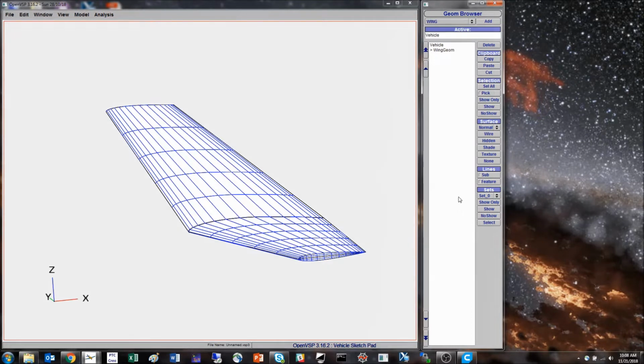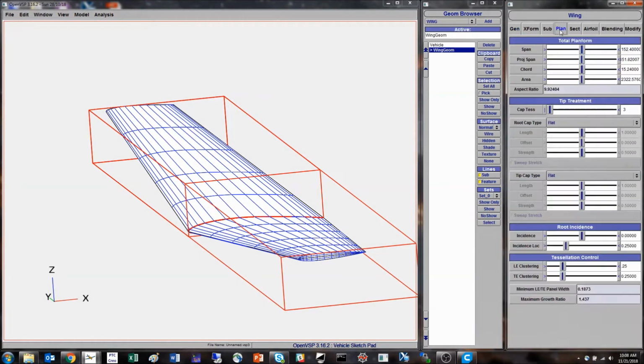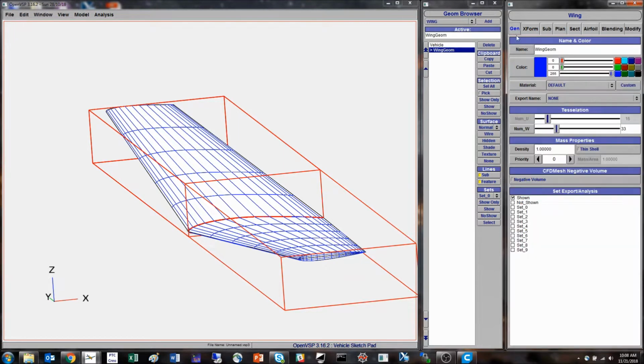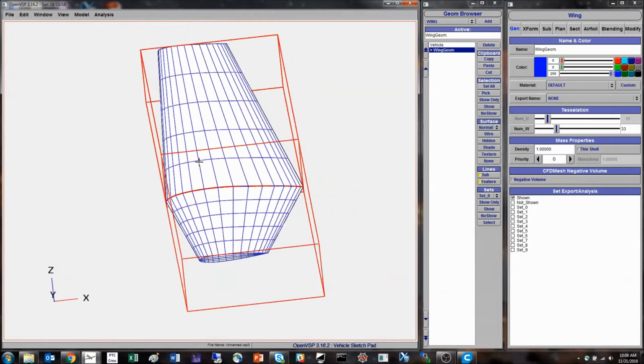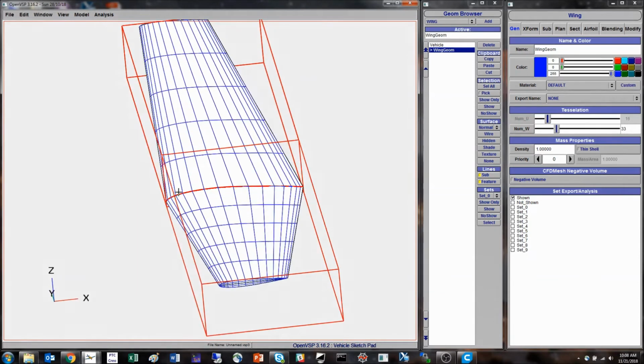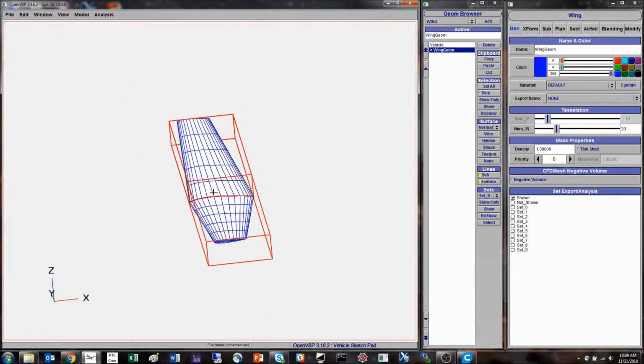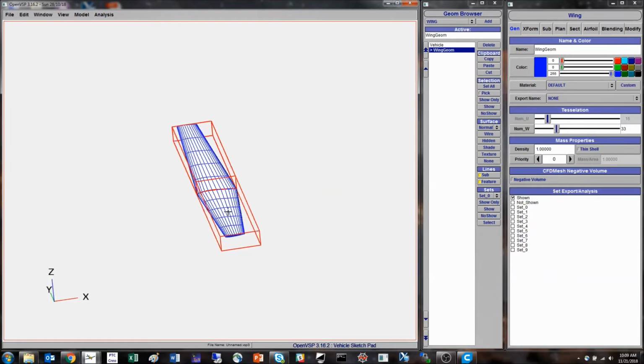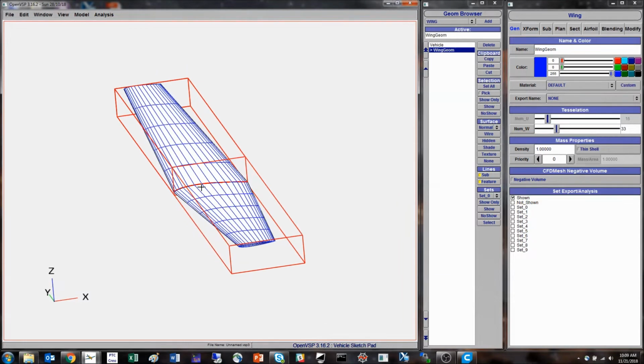So to begin, we've got the model that we finished with in the wing design video here that's already scaled for millimeters at a 6-inch span. That's 152.4 millimeters and an area in square millimeters. Now, you'll notice that the wing looks right. It's got a nice sweep, it's got a nice taper ratio, the aspect ratio looks pretty good, and you may think, okay, we're ready to go.